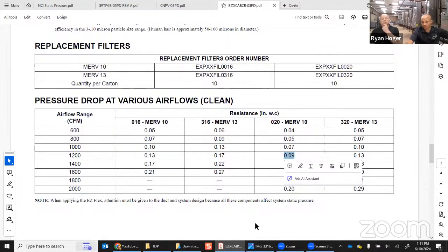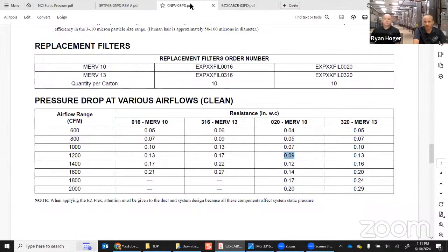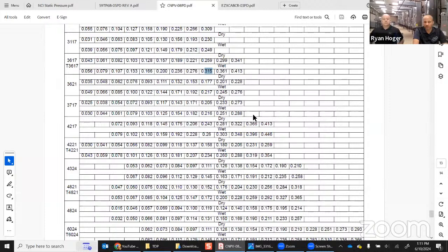Obviously, bigger filter, more surface area, wider duct, so less pressure. Small restrictive ductwork contributes to your pressure problem. Larger, less restrictive ductwork and or filters helps your static pressure problem. Let's say, for sake of argument, that's 0.1, and you got 0.3 off the coil. That's 0.4 of a furnace that's prepared to deliver 0.5 to you.